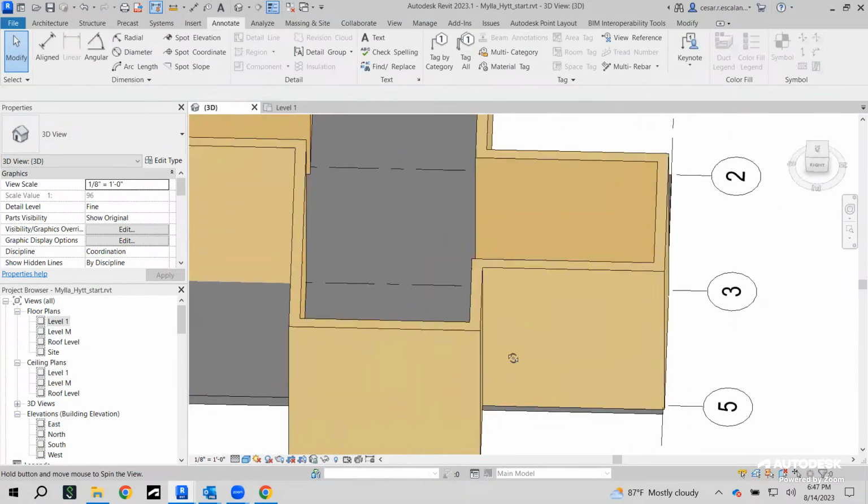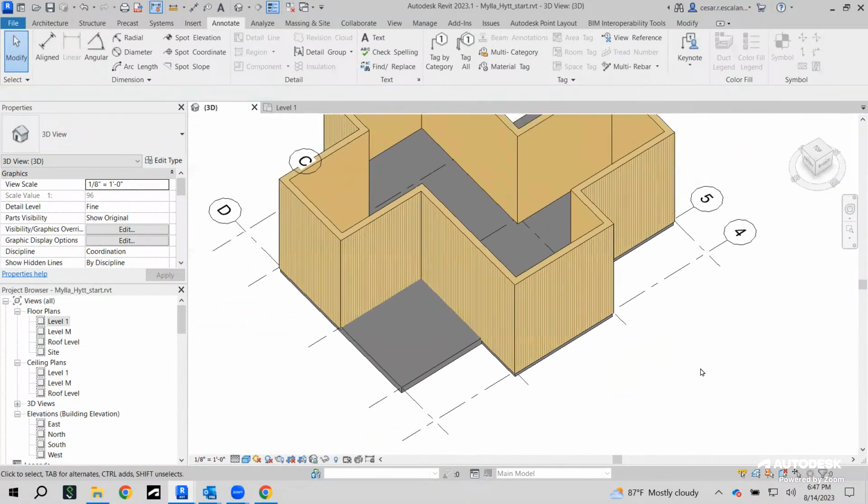Something that's pretty cool with what you're showing, and that I've had the opportunity to do before, is that you can actually split your wall into multiple layers vertically. So if you have like a 6 inch, 8 inch, 10 inch curb, you can put that on the bottom. So you can have as many different wall types stacked on top of each other as you want, which is pretty cool. Yeah.